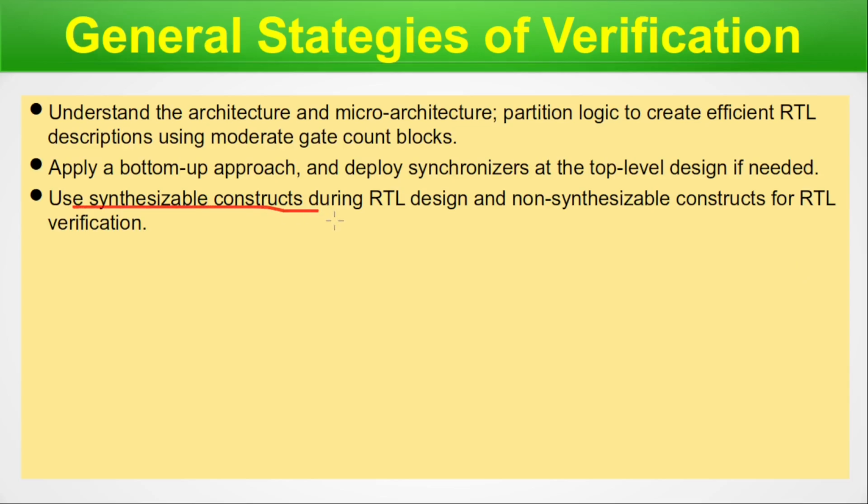Use synthesizable constructs during RTL design and non-synthesizable constructs for RTL verification. Why do we say that? We have an entire episode in the Verilog series where we talked about synthesizable versus non-synthesizable Verilog. Verilog has some constructs which are very useful. However, they are not synthesizable, that is, you cannot transform them into a gate level netlist.